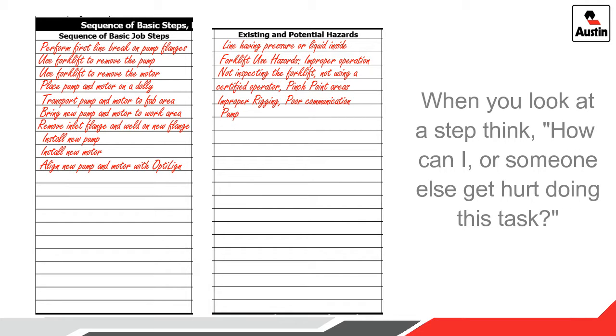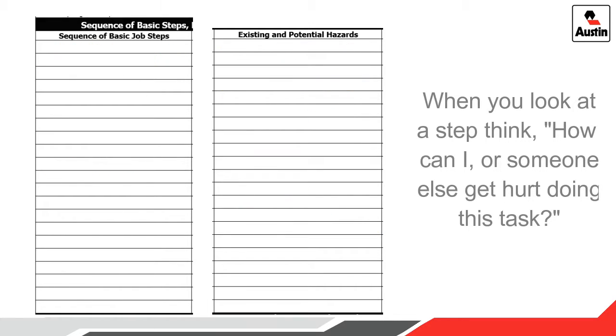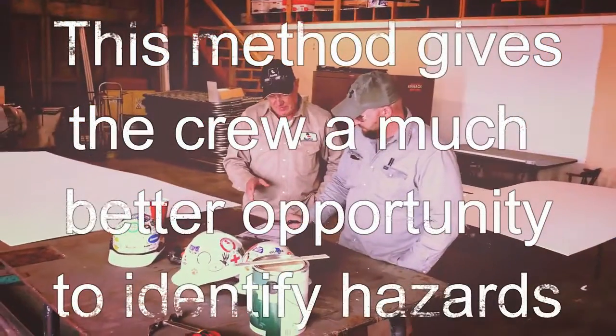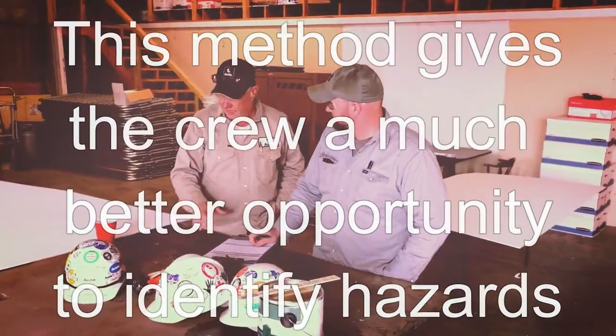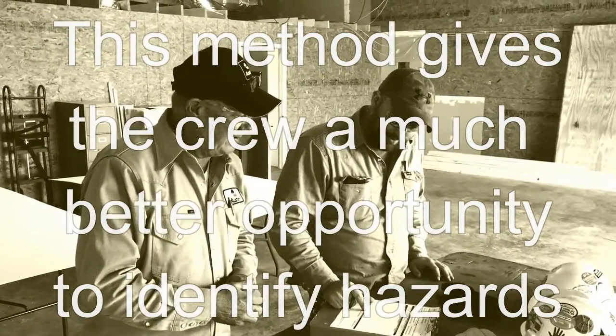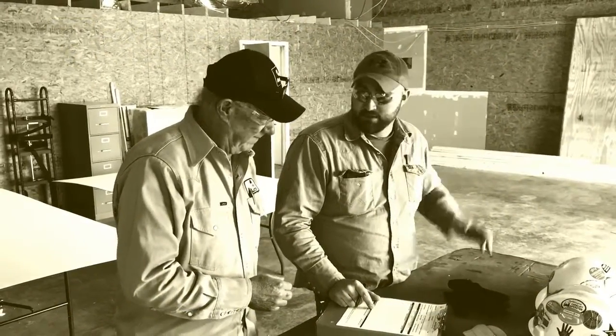Step 4 is placing the pump and the motor on the dolly. Some hazards include load shifting and not being secured. And this goes on until you have analyzed each step and identified the hazards involved. Doing it this way gives the crew a much better opportunity to identify hazards than if you were just looking at the job as a whole and trying to come up with the hazards.